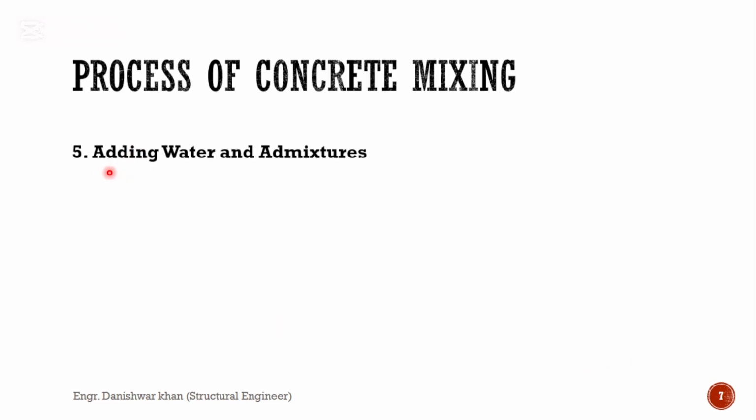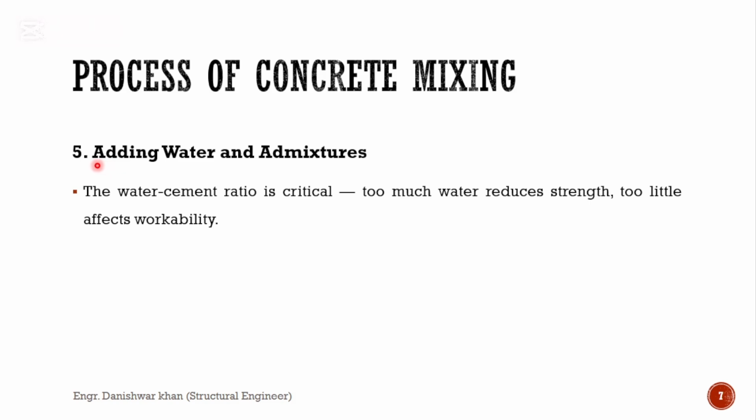Standard mixing time is generally between 1.5 to 3 minutes in a mechanical mixer to ensure uniform consistency. Proper mixing ensures the concrete is homogeneous and workable.